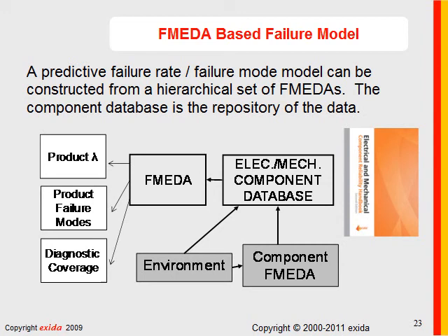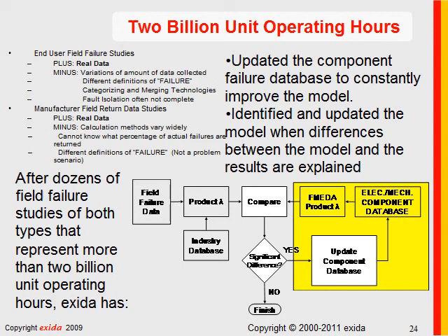Given an electrical and mechanical component database, the FMEA technique can be used, as I've said, to generate product failure rates, product failure modes, diagnostic coverage, and actually even estimate useful life and proof test coverage for manual proof test techniques. There's quite a few things that can come out of this analysis.